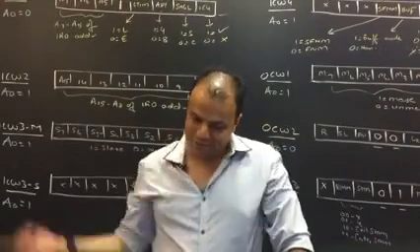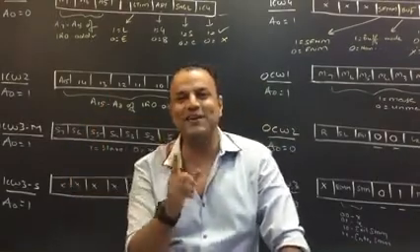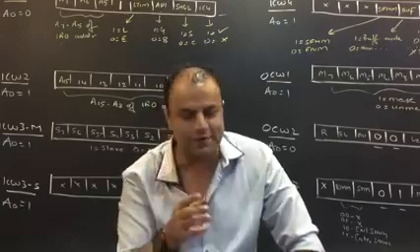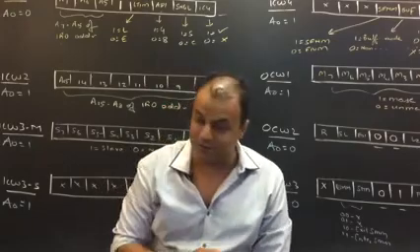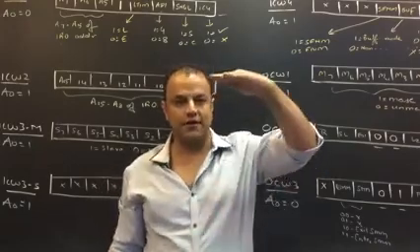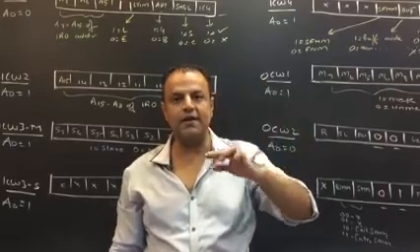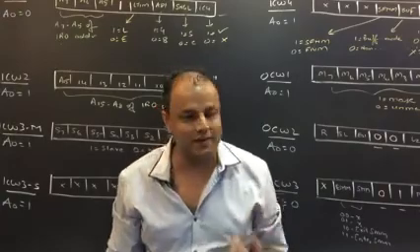That interval is also your choice, whether you want an interval of 4 or an interval of 8. If you've viewed the last video properly, the architecture video, I've explained all of this. So I say again, you give the ISR address of IR0. The remaining addresses are taken at an interval. The interval can be of 4 or 8, and that is also chosen by the programmer.